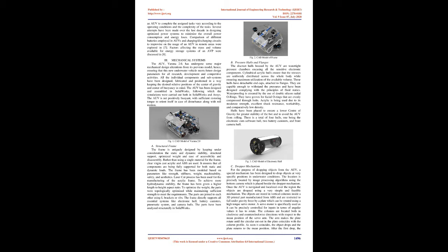The AUV has been designed and assembled in SolidWorks, following which the simulations were carried out both in SolidWorks and ANSYS. The AUV is net positively buoyant, with sufficient restoring torque to orient itself in case of disturbance along with roll motion.